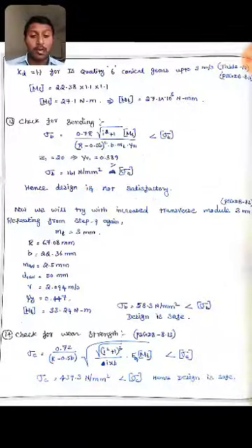Design MT is equal to 33.24 Newton meter. So now finally we get sigma b is equal to 58.3 Newton per mm squared for revision, which is less than design sigma b. Hence the design is safe.